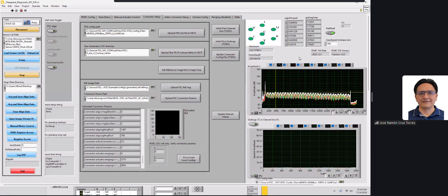Anything above 0.3, all the way up to about 0.6, just means that you have coupling and you're using the right cal file and the right cores, but the signal's just not good enough. The signal-to-noise ratio is so bad that the shape sensing algorithm can't use it. It's probably going to give you a lot of errors. So that's a lot of the actual shape sensing and optics stuff.